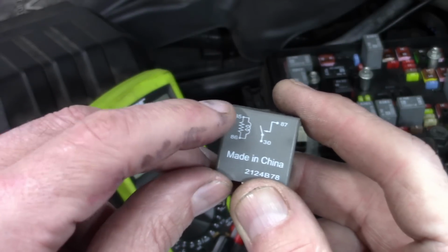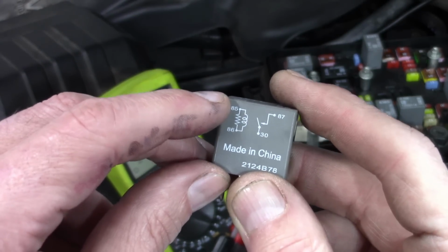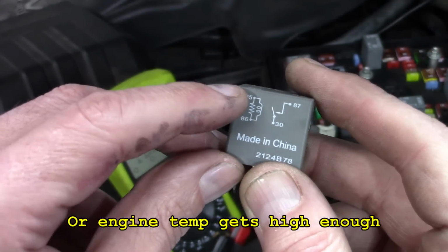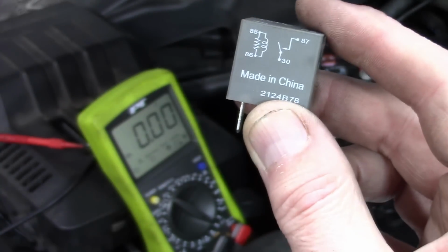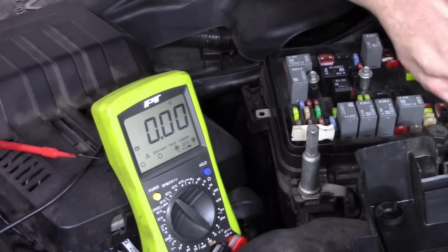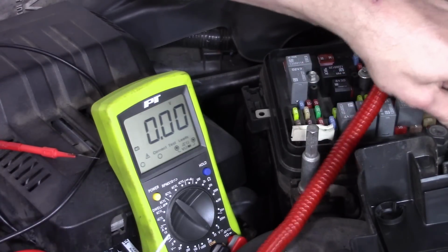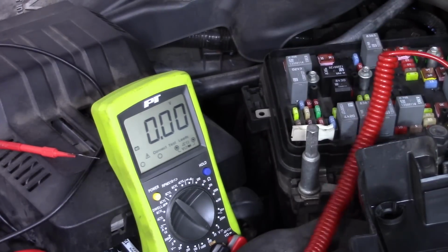The user of the vehicle will need to do some type of ground side control, turning on the AC, whatever it is, in order to complete the circuit through our control side, activate that magnet, and then pull our switch closed here. Okay, can we do this with a test light? Absolutely we can. It makes no difference, especially in this case, because we just need a qualitative result. We just need to see, do we have power, do we not? We don't really care how much.